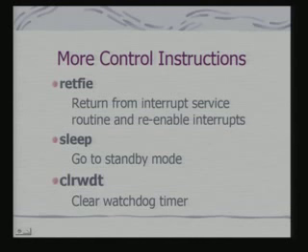You can clear the watchdog timer, because if the watchdog timer finishes its counting after a particular time period, it is supposed to reset the system. Ideally it should reset the system, and I have already discussed why a watchdog timer is required. If you do not want the watchdog timer to really reset the system, you would like it to be cleared or reprogrammed periodically. So this clear watchdog timer is an instruction for clearing the content of the watchdog timer.